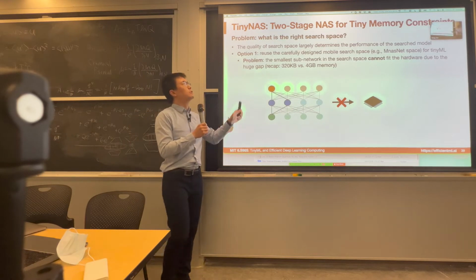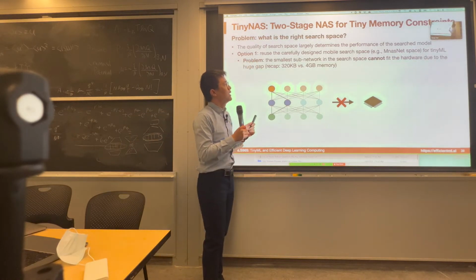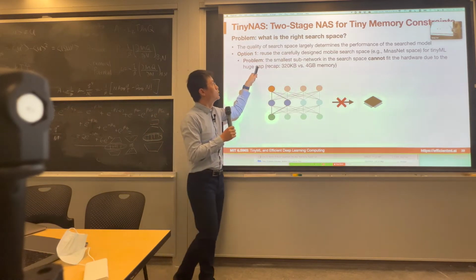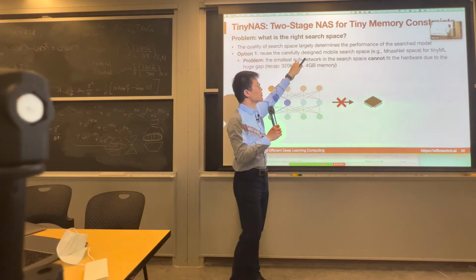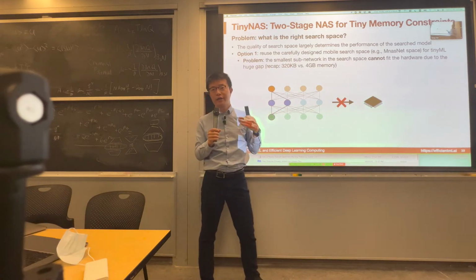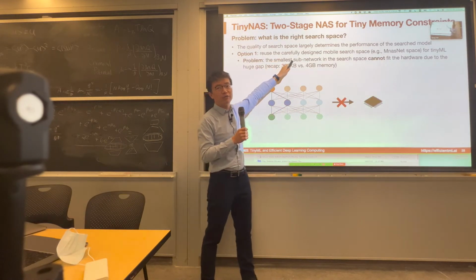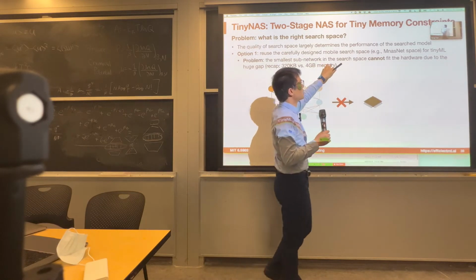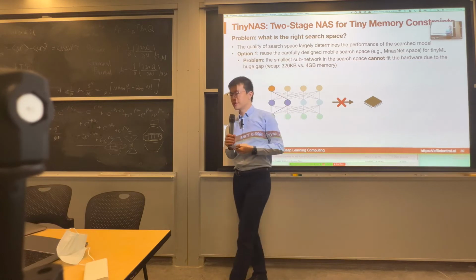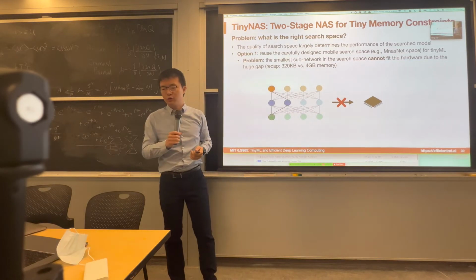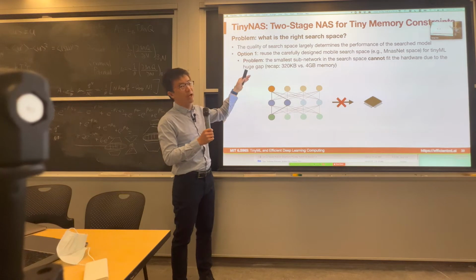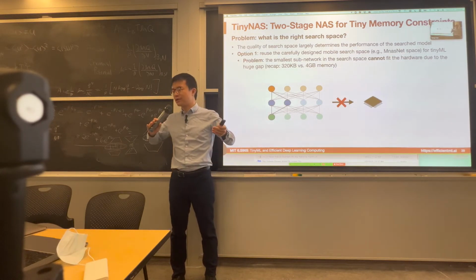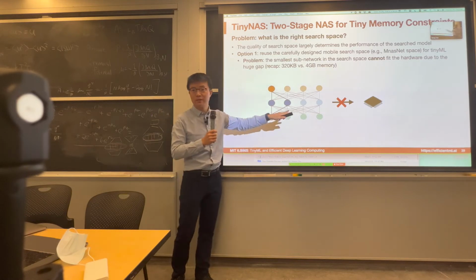So there are several options, right? What determines a good design space? Option one is to reuse the prior design spaces that are carefully designed by other teams, for example, MNAS space, MobileNet v3 space, once-for-all space. However, those search spaces are actually designed for mobile devices, like mobile phones, which have much larger computational capability than a microcontroller.